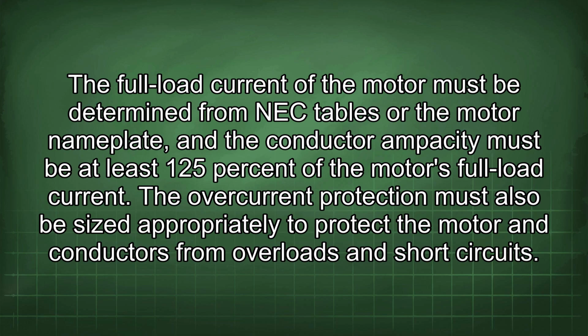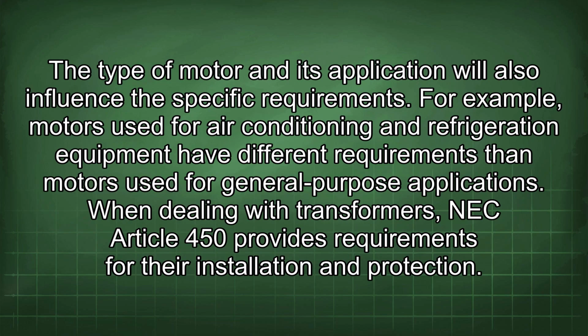The overcurrent protection must also be sized appropriately to protect the motor and conductors from overloads and short circuits. The type of motor and its application will also influence the specific requirements. For example, motors used for air conditioning and refrigeration equipment have different requirements than motors used for general purpose applications.